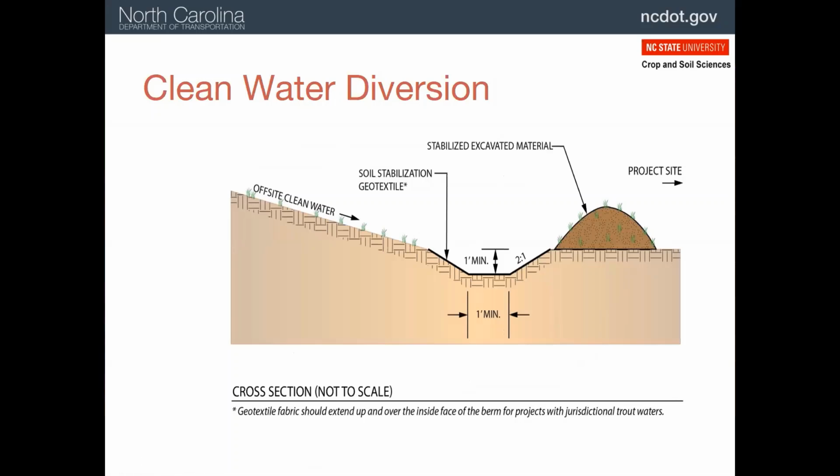And again, any areas that are excavated around where we're having water flowing, we want to make sure there is grass so that we're not seeing a lot of sediment moving into that ditch from that area right adjacent to the diversion.